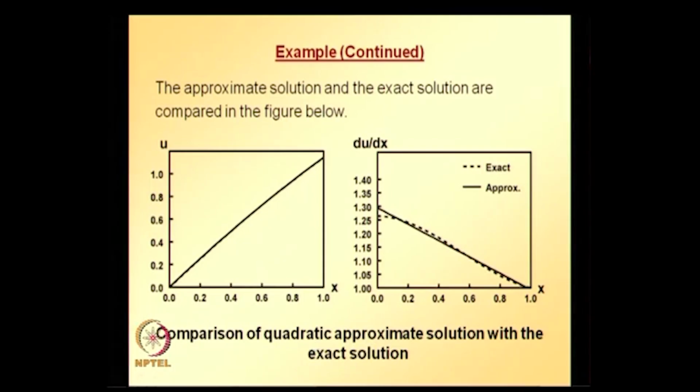So you can start with a cubic polynomial as a trial solution and follow the same process. Once you make an assumption of some approximate trial solution, before you proceed any further, make sure that it is admissible by making sure that it satisfies the essential boundary conditions. Then you plug that admissible trial solution into the equivalent functional and apply the stationarity condition to get the unknown coefficients, solving the simultaneous equations that you get.